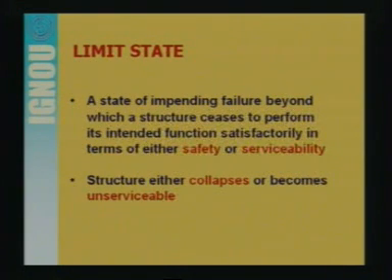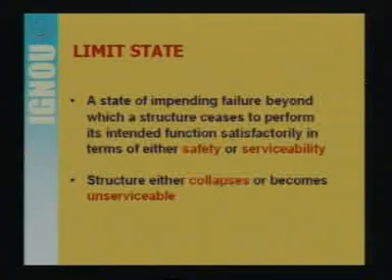Now, today I shall start the lecture with a little recall of some important points that I discussed in my last lecture regarding the limit state design of flexural members. First, let us see what limit state design is. In our last lecture, if you remember, we defined the limit state as a state of impending failure beyond which a structure ceases to perform its intended function satisfactorily in terms of either safety or serviceability. So, two terms are there, safety and serviceability. This limit state talks about the safety of the structure and the serviceability of the structure. Now, a structure either collapses or becomes unserviceable after reaching the limit state.